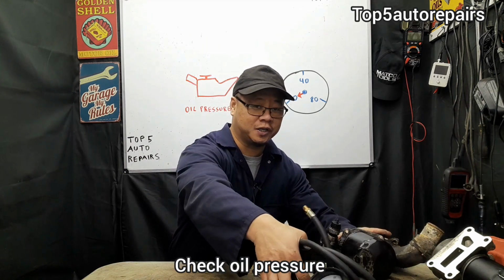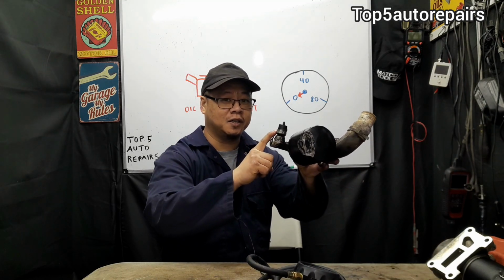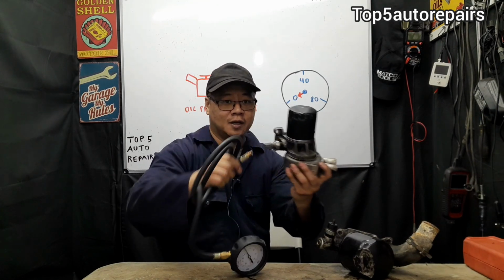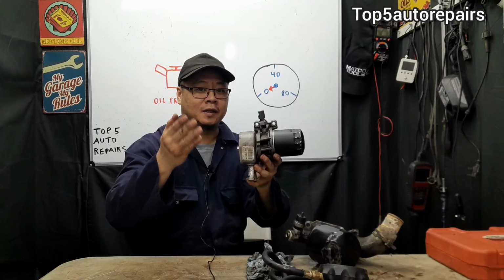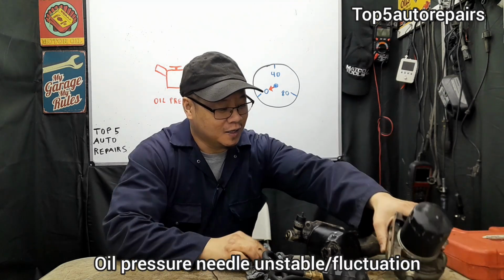At this point, it is important to check engine oil pressure by using an oil pressure gauge. What you have to do is remove the oil pressure sensor or switch, install the oil pressure gauge on it, and run your engine. You want to check oil pressure at idle, and you want to check it at higher RPM by comparing it to manufacturer specification.